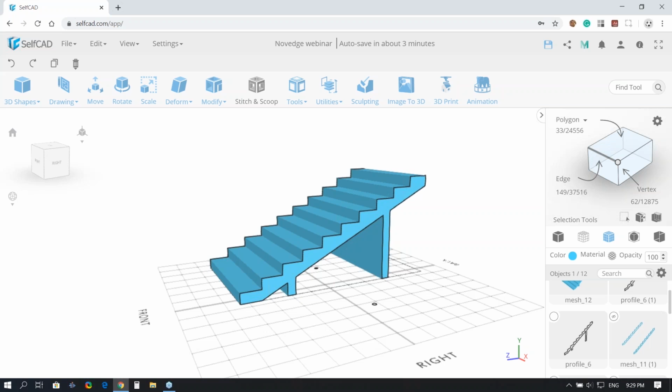So what I'm going to do now is show another idea of what you can use with the Loft tool. It can do follow path. You can do a lot of things, but in this case, I'm going to go to the drawing again, and I'm going to draw a small rectangle in 3D Sketch. It doesn't really matter where I position it, so I'm just going to position it over here. Let's say 20. I have to click 20 to give it the size, and then I have to drag it out. So I'm going to make it a size by 200, let's say.